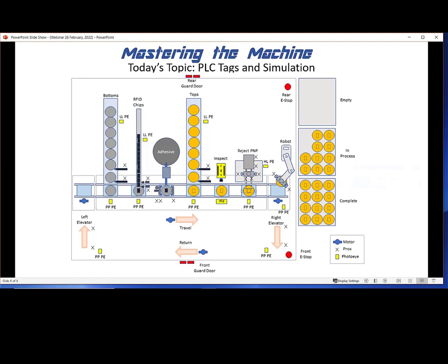So we had some interesting conversations, for instance, about safety systems, and they don't even use dual channel e-stop circuits, which I was kind of surprised to hear. But when you think about it, most of their safety is handled in a different way. When you hit the e-stop in those companies, you're really not necessarily protecting personnel. You may be shutting down the system, but they have further safety systems behind those, I'm sure, that probably supersede the dual channel circuits that we're used to.